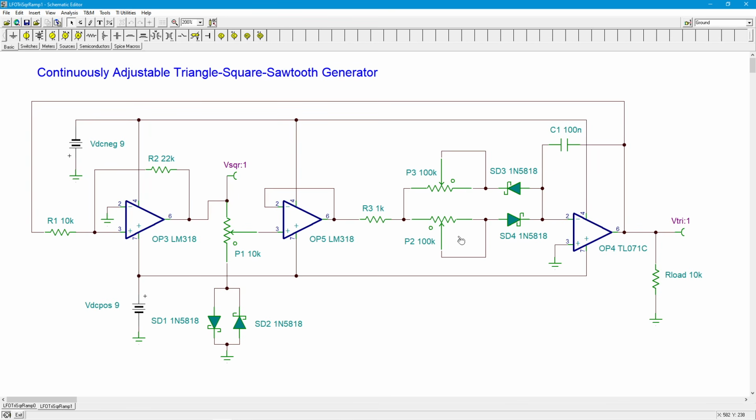So, not so great. All right, what else can we do? Well, instead of attacking the resistance, remember, it's the current charging and discharging C1 that really matters here. So what I can do is change the voltage that feeds this whole thing. That's what this pot does, right? So this is saturation. And now we control a percentage of that, which is going to drop out here.